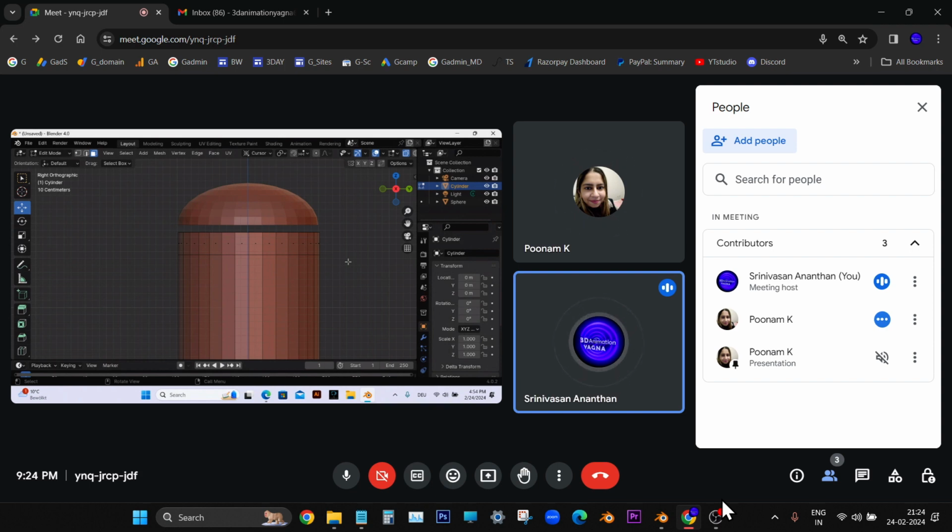Okay. So now you can press. Take your cursor to the face, that set of faces that we have added, and hold Alt on the keyboard and then select the same face. Yes, now you got it selected. Very good. Now press Alt E. Yeah, second option.